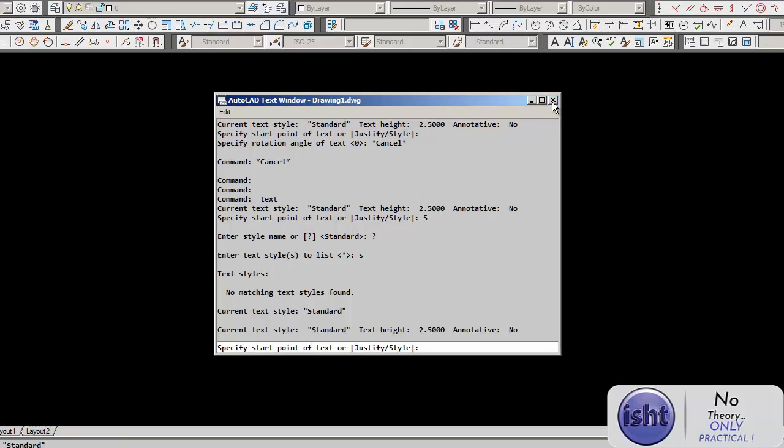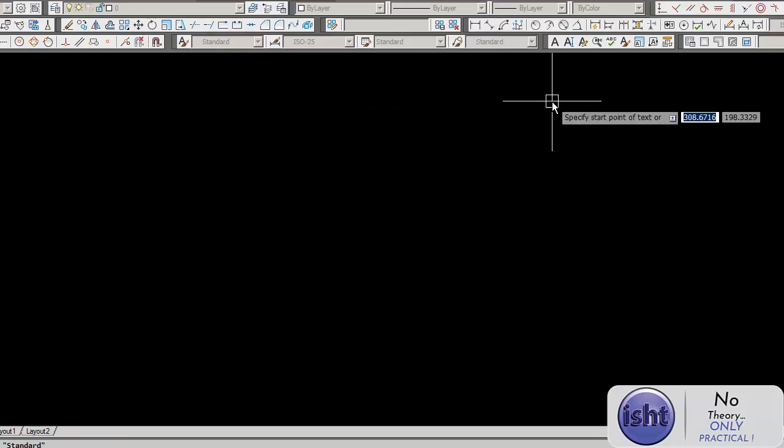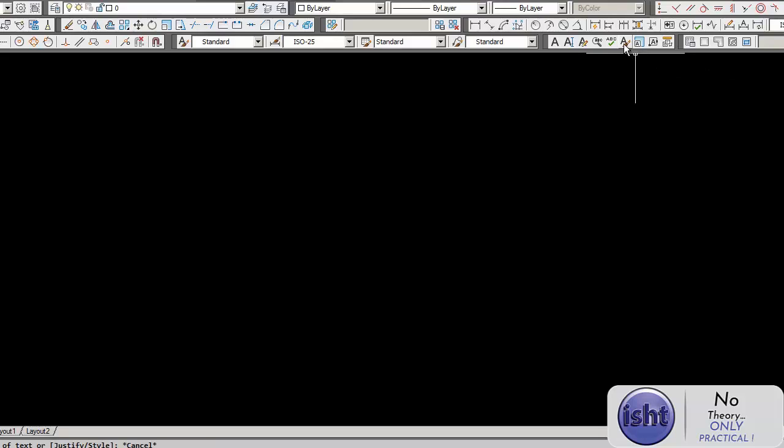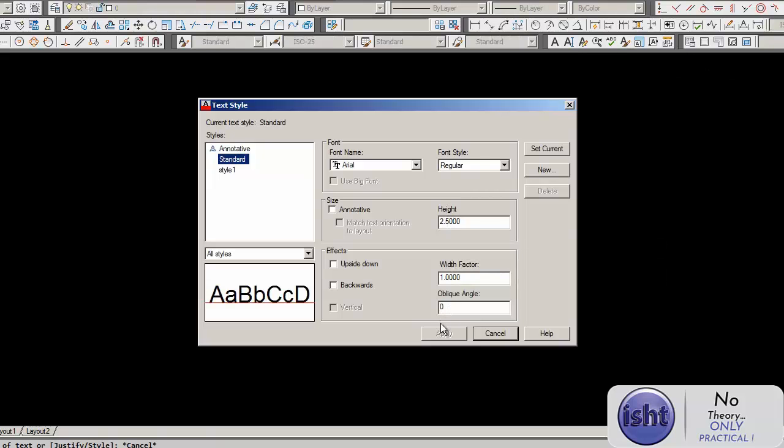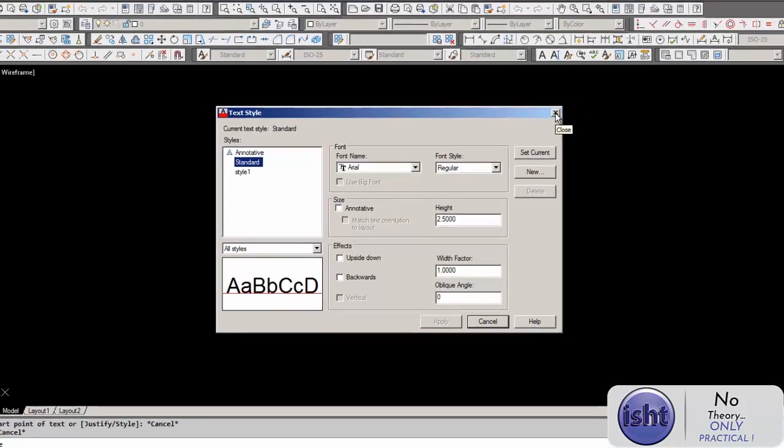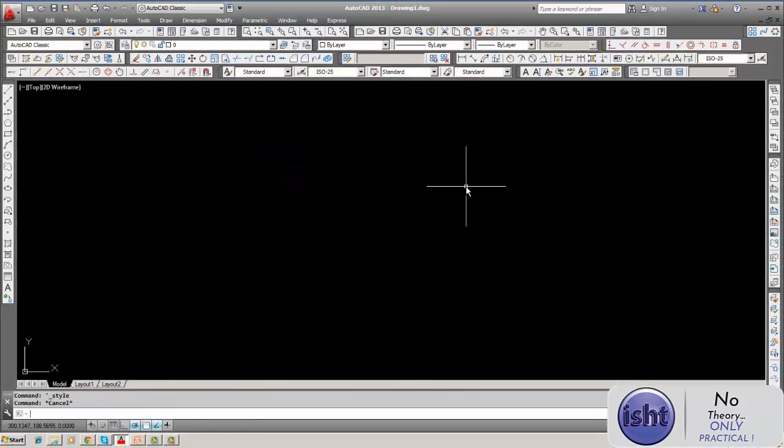So it is not there. So you have to select the style from here only. There is a menu because there are some changes in the AutoCAD revisions. Earlier the different styles used to come out in the style option itself. Now we can just select from here. This is about single text line.